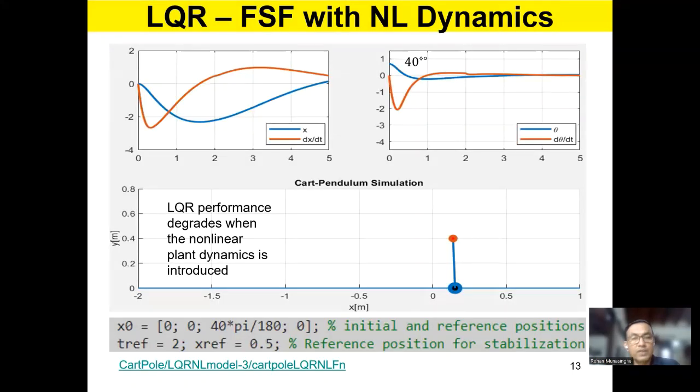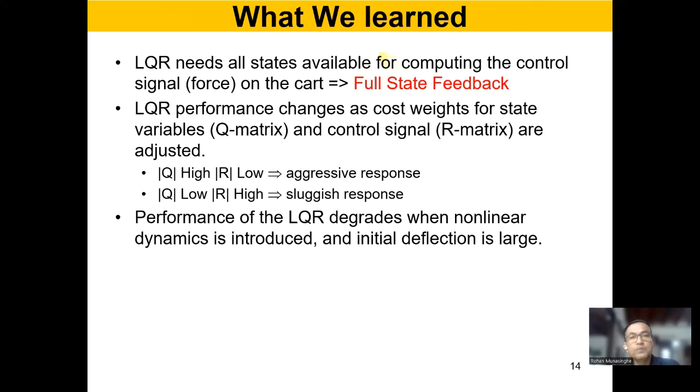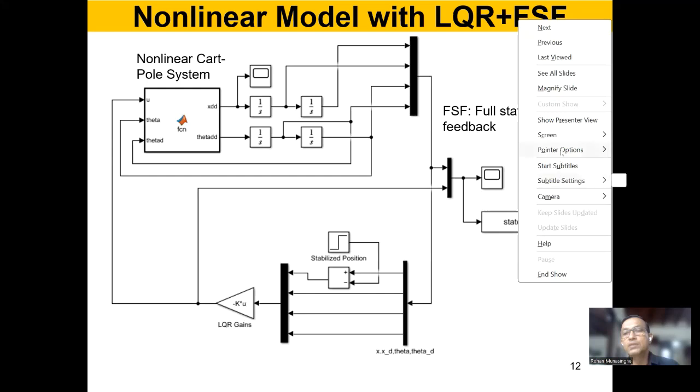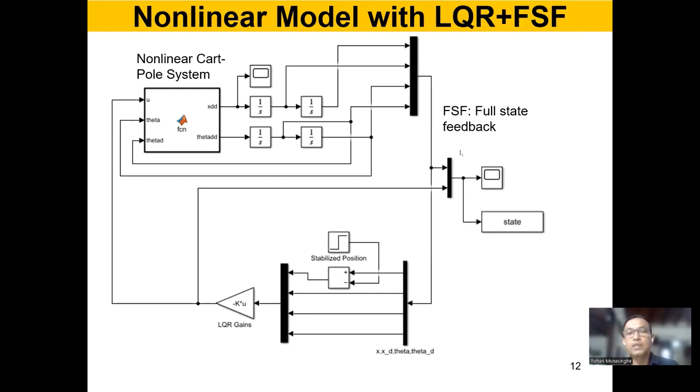Now, what is next? We can do something really interesting here. Can we use the same linear quadratic regulator that we designed and built based on the linear model? Yeah, using the same linear quadratic regulator. What if we replace the linear model with the actual model? The actual model in Simulink, you can do that using a Simulink function.